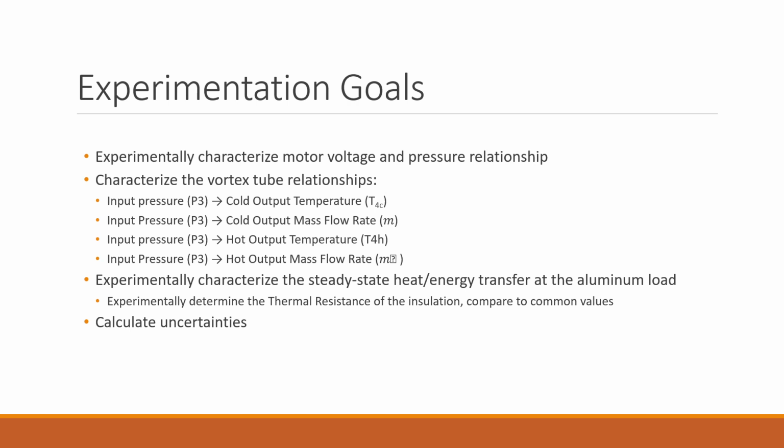So throughout our experimentation, we have a couple of goals that we had to keep in mind. One of them being that we needed to characterize the relationship between the motor voltage and the output pressure that was being put into the system. The relationship between the input pressure as well as multiple different outputs also needed to be determined. Those outputs being the cold output temperature, the cold output mass flow rate, as well as the hot output temperature and mass flow rates as well.